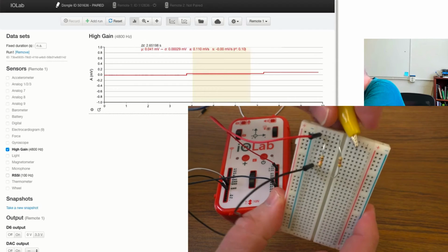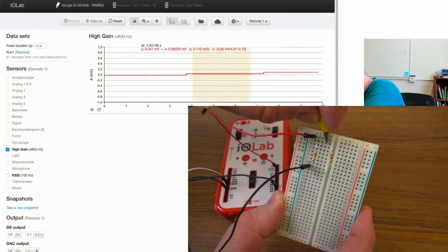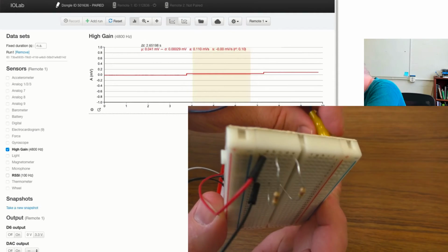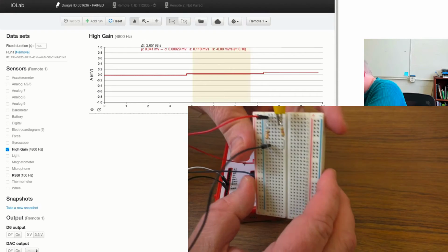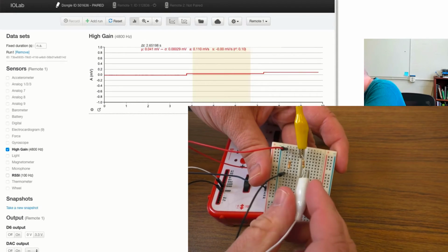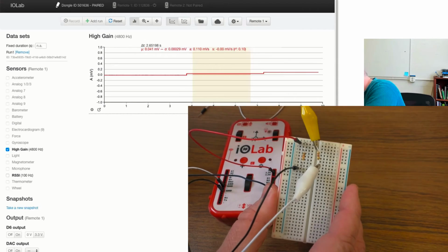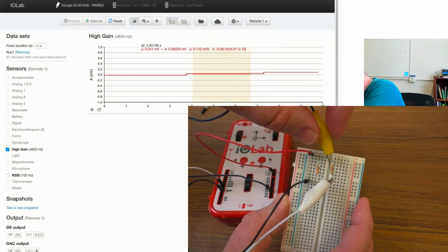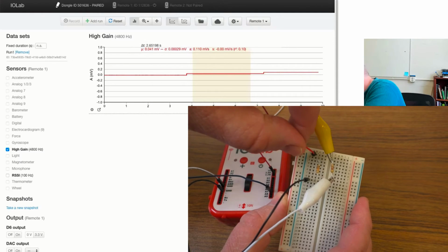Okay, so this is important here because if we just were to use regular jumper wires and plug it in, we're not going to get the voltage drop across just the one resistor. So the A7, I'm going to plug into the top side. That's the same side that's connected to the 3.3 volt port.